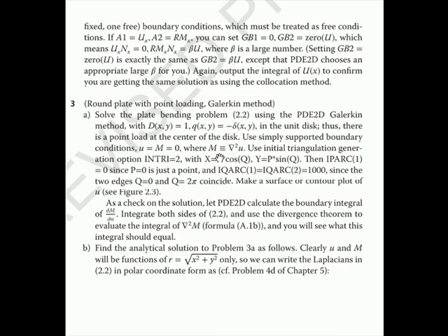So again, you define the Laplacian of u, uxx plus uyy equals m, mxx plus myy equals q, which is minus this delta function. And you're going to solve that with simply supported boundary conditions on the entire boundary.